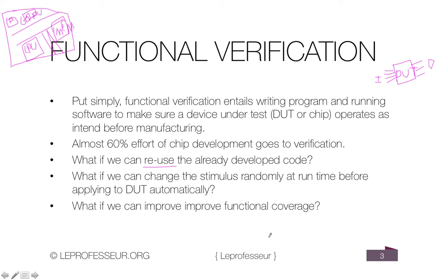Typical hardware design languages, say VHDL or Verilog, are very good when you want to write code which a synthesis tool is able to synthesize. But for verification, you need some extra features. For example, you need an object factory which can generate different kinds of objects. Objects here may be a stimulus, and those objects, based on certain parameters, are randomly configured and drive a stimulus to your DUT. We need all those features to optimize our verification effort.